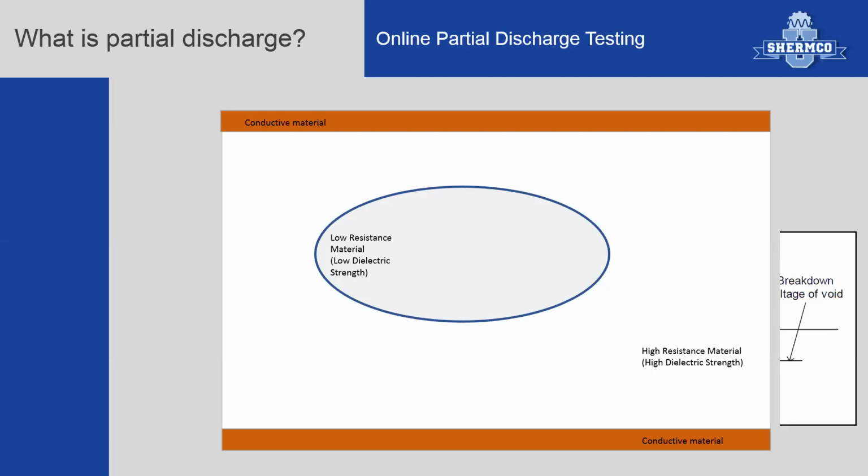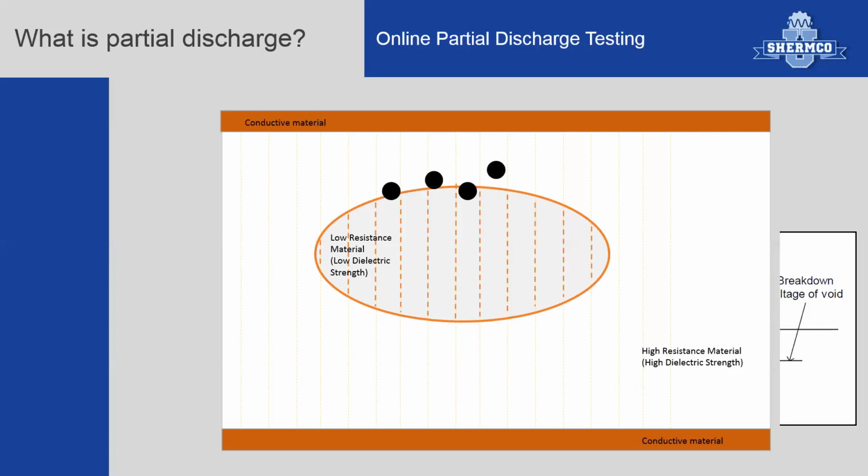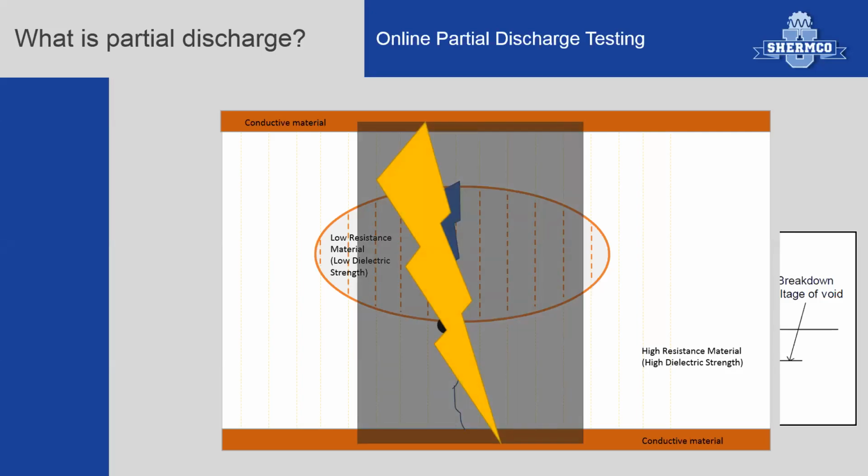As a voltage is applied, the voltage stress across the air gap is higher than on the insulation. The walls of the gap are stressed and begin to break down or ionize. Now, eventually, these ions build up and the resistance of the air gap breaks down, and a discharge occurs across the gap. Okay, this can potentially leave semiconductive residue or carbon behind, which is conductive, kind of like a stress crack on the insulation. Now, over time, this will build and can lead to or create a full discharge, as we kind of walk through there in that little animation.